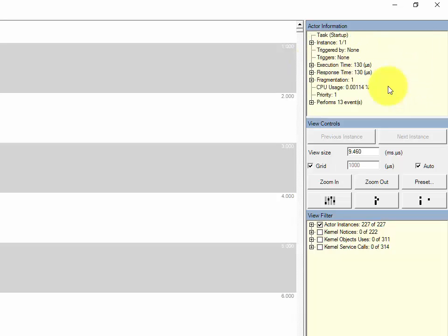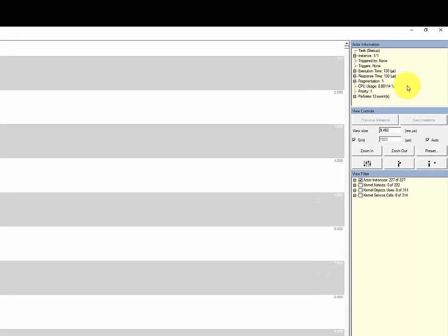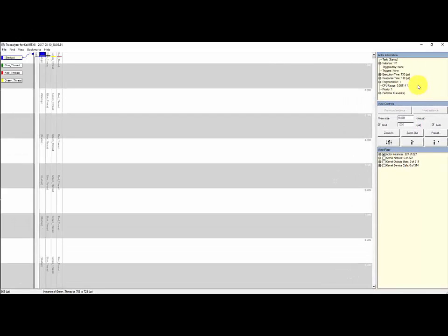Now, if I wasn't using a real-time operating system, if we're thinking back to when you're using an 8-bit or 16-bit microcontroller, you don't get to see all this level of detail. Instead, what happens is you have to try to blink LEDs, you have to try to use printf messages, you have to try to figure out ways to let yourself know that, hey, something's happening to my system, but you don't necessarily know what it is. Using these tracing capabilities, though, we're not guessing what the microcontroller is doing or what lines of code it might be executing.